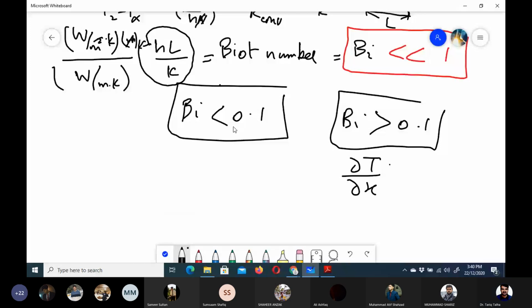Okay, so here this capital L is the thickness of this material. But usually when we talk about die casting, we have not a rectangular object, but maybe a random volume, some part which has been die casted. So for that, this characteristic length, this thickness, is very hard to define.